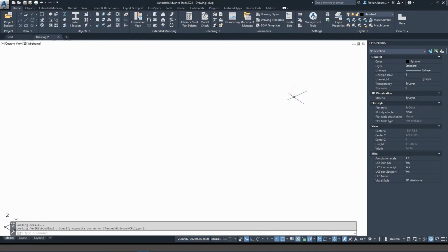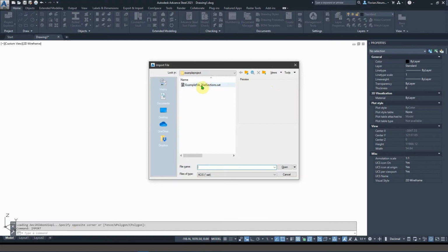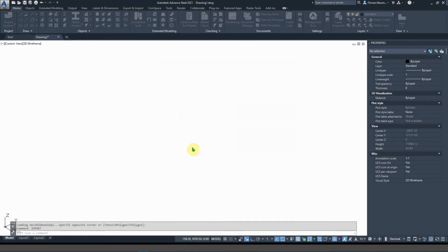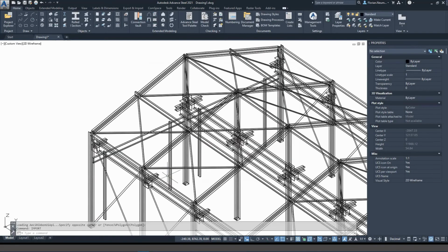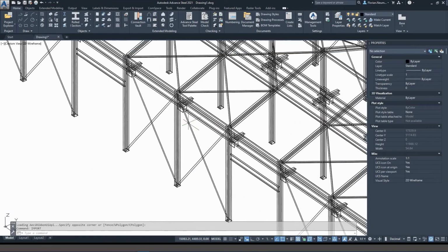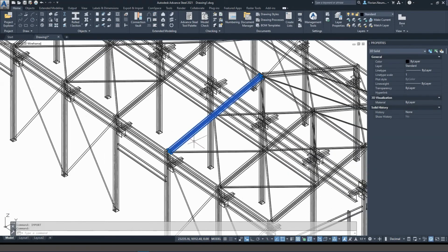Sounds like a plan. So welcome back to Advanced Steel, and we want to see how we can now import our Navisworks export. So remember, we exported this as a set file. We can just go to our import folder, have our warehouse NWD, open this up, and we should see somewhere, somehow, our solids we have exported with the help of iConstruct.